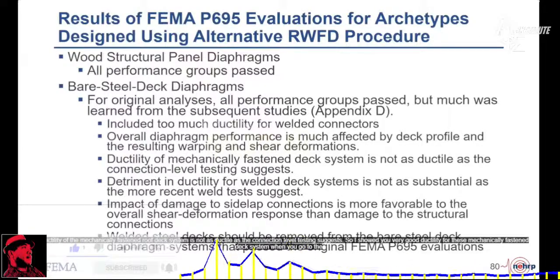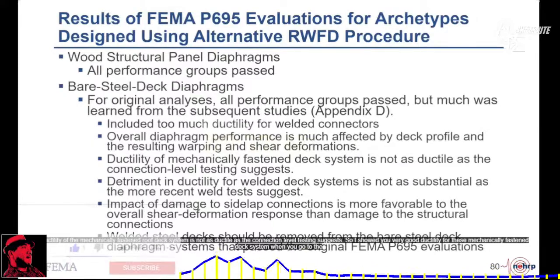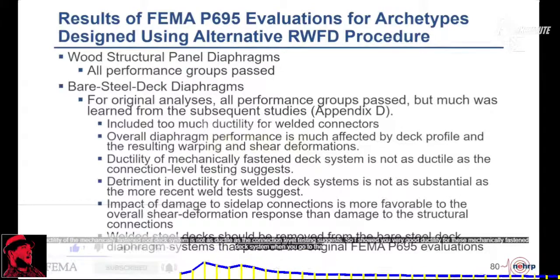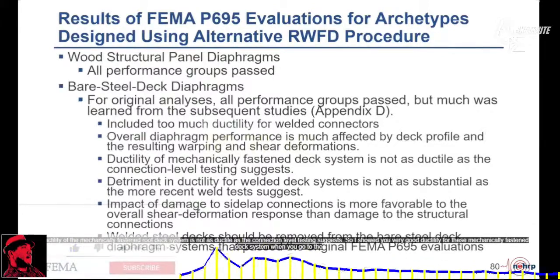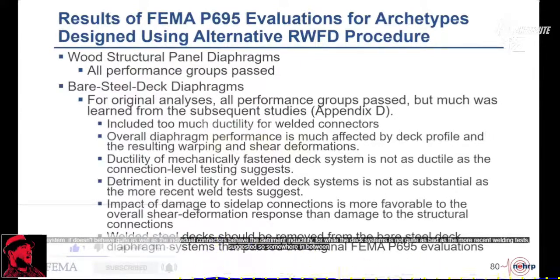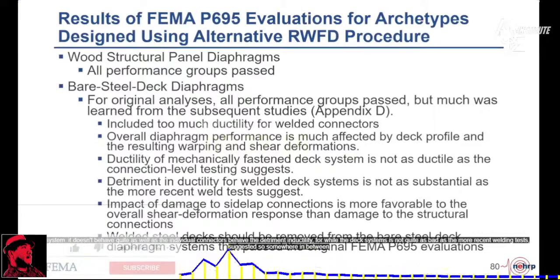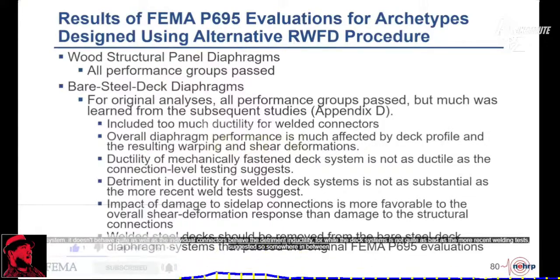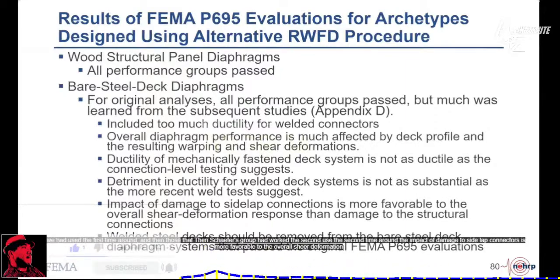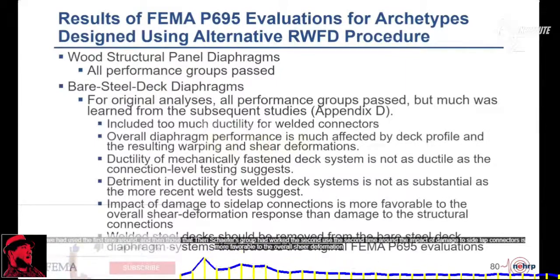The ductility of the mechanically fastened roof deck system is not as ductile as the connection level testing suggests. I showed you very good ductility for these mechanically fastened deck systems, but when you go to the whole system, it doesn't behave quite as well as the individual connectors. The detriment in ductility for welded deck systems is not quite as bad as the more recent welding tests suggested. So it's somewhere in between what we had used the first time around and what Ben Schafer's group had used the second time around.